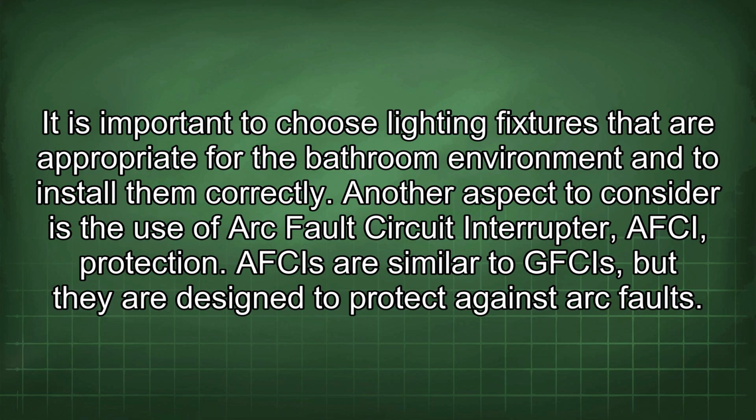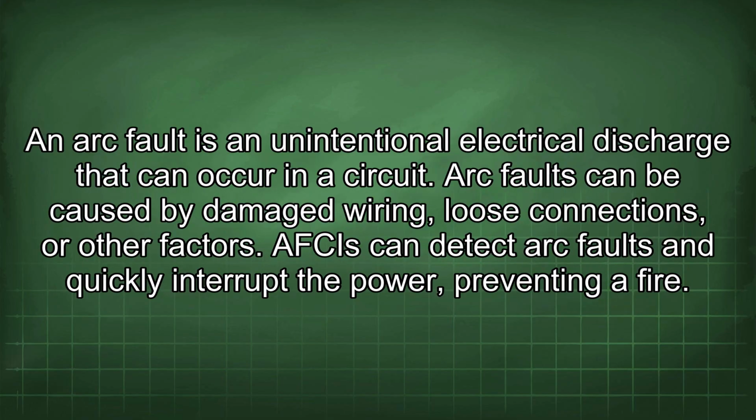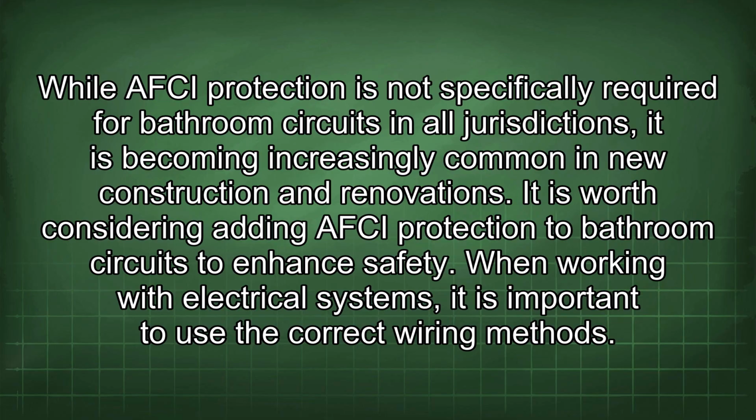Another aspect to consider is the use of arc fault circuit interrupter, AFCI, protection. AFCIs are similar to GFCIs, but they are designed to protect against arc faults. An arc fault is an unintentional electrical discharge that can occur in a circuit. Arc faults can be caused by damaged wiring, loose connections, or other factors. AFCIs can detect arc faults and quickly interrupt the power, preventing a fire. While AFCI protection is not specifically required for bathroom circuits in all jurisdictions, it is becoming increasingly common in new construction and renovations.